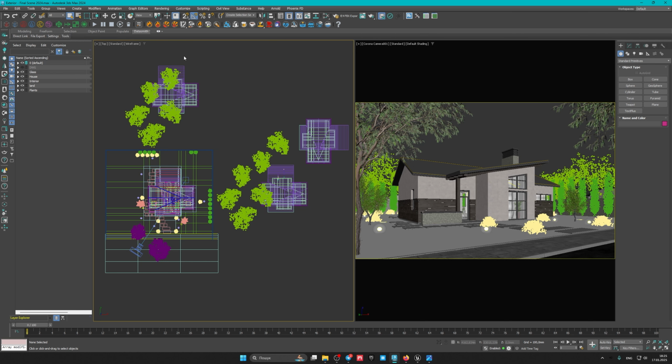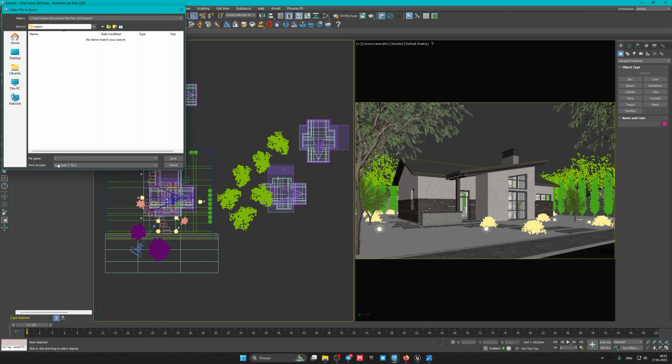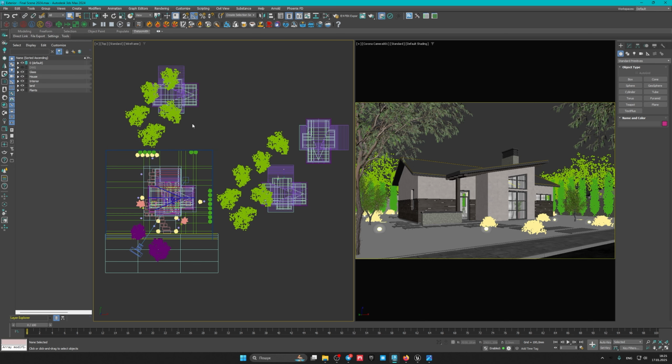If it's an older Max 21, exporting with Datasmith is done through File Export, and here, instead of FBX in the list, you can choose Datasmith. After 21 Max, it moved here to the ribbon. So we have two options for working with Datasmith. The first is simply File, Export, either exporting the entire file or the selected geometry. The second option is Direct Link.